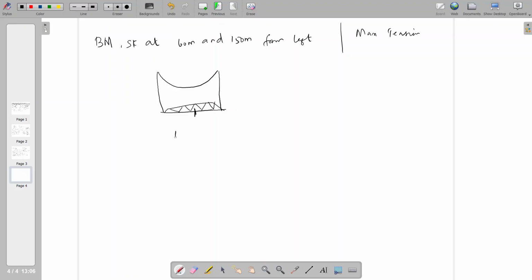So our center position is 100 meter. It is asked at the level of 60 meter. So we need this y, the section vertical distance y at 60 and also y at 150 meter. Another section is 150 meter. We can consider 50 meter from the right side to use the parabolic equation to find the vertical ordinate y at 150, which is equal to y at 50.